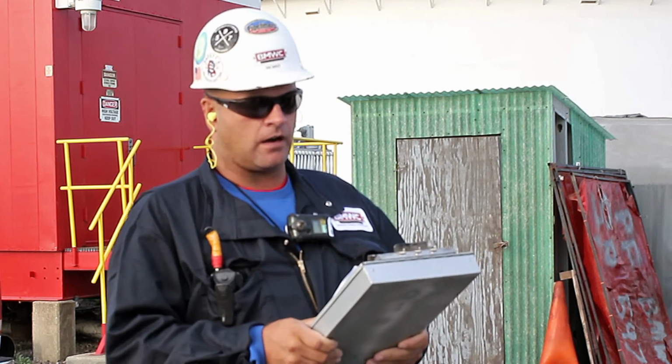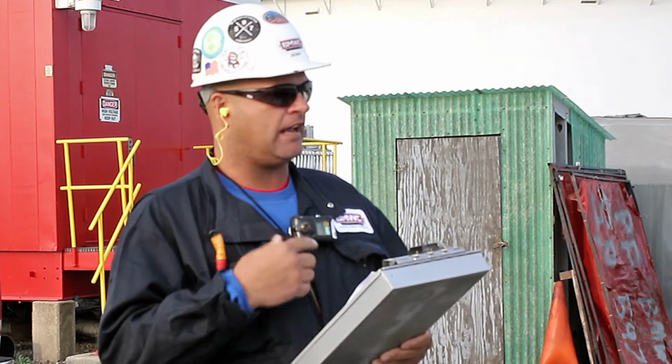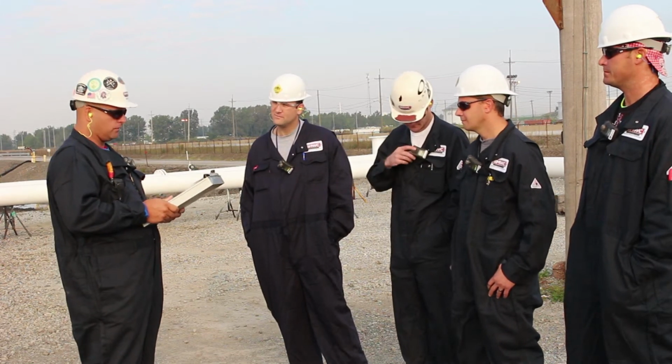We're going to have a fresh air trailer today too. Hard hat, safety glasses, and ear plugs are at a minimum. Is everybody's monitor up to date? Yep. Okay. When we go in the hole, we're going to have a 4-gas meter with us too.